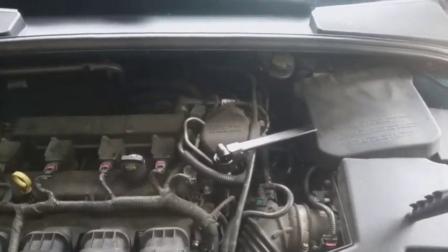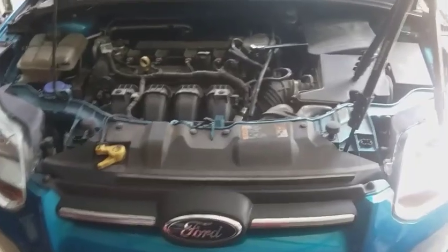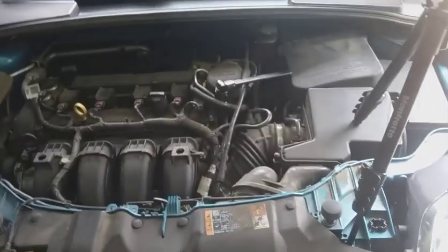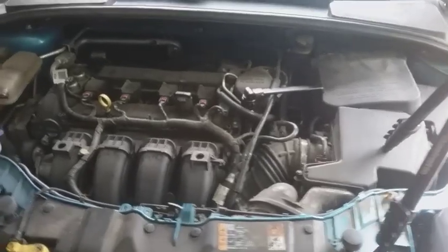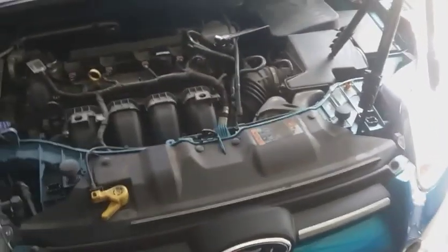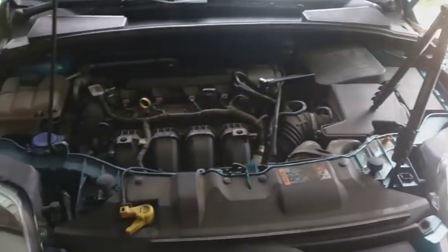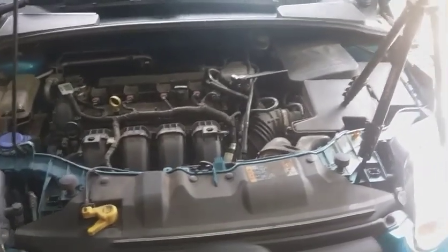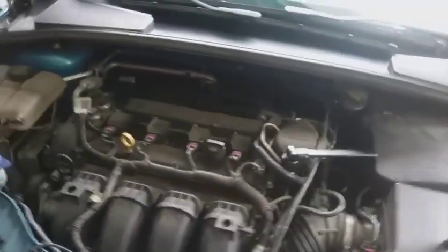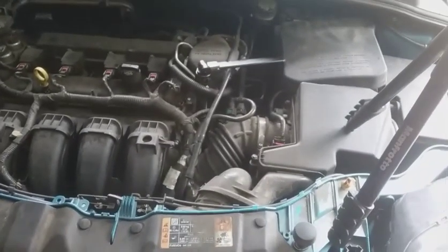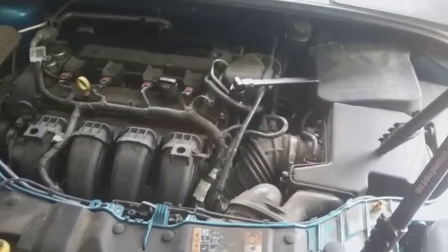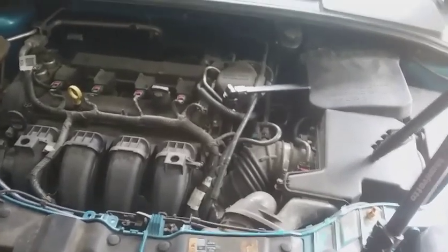What's going on with this one? If anybody recognizes Ford Focus, it's going to be the 2014 Focus. It's the SE Flex Fuel. But what's going on is the car's stalling, and it's stalling for a reason I'm going to assume from what she described is going to be this purge valve here. How I concluded is, well, when she gets gas, it stalls.